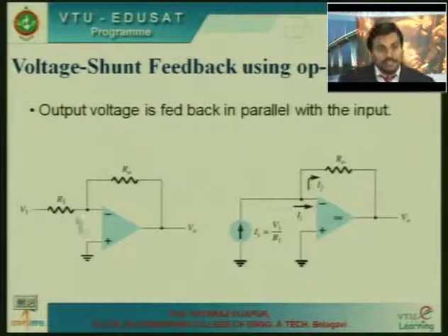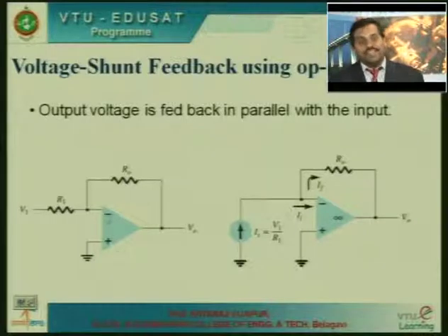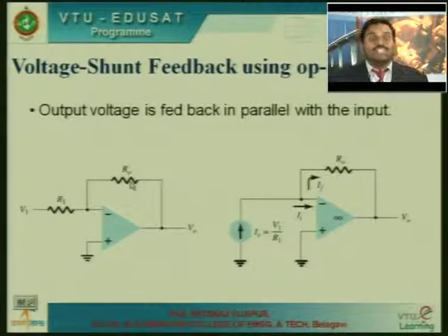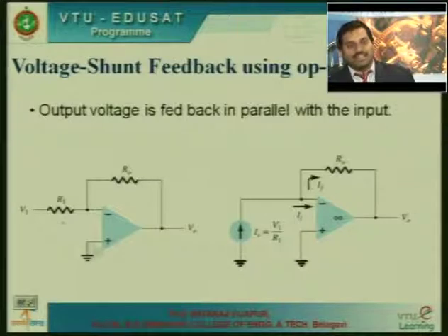Okay, so you can note down this diagram. This is an op amp connected in an inverting amplifier configuration. This is the input voltage Vi. You have a resistance R1, you have a resistance R0. R0 is a feedback resistor here, which is connected between the output and the input. So it acts as a feedback resistor. It is connected between the output and the inverting terminal. Then the non-inverting terminal is grounded here.